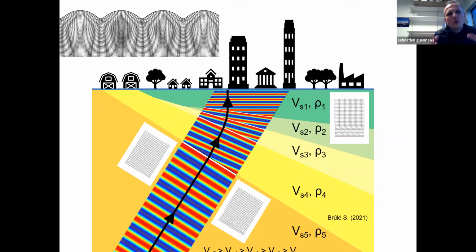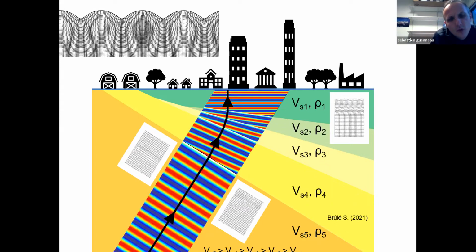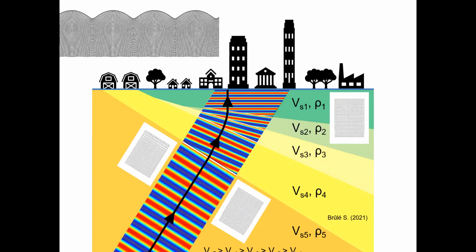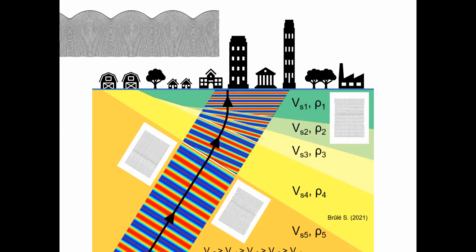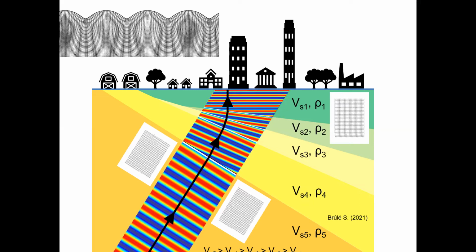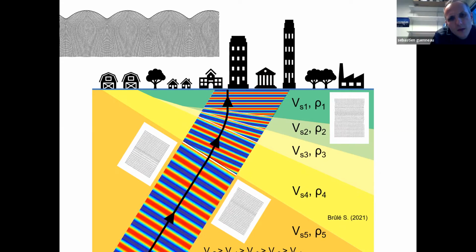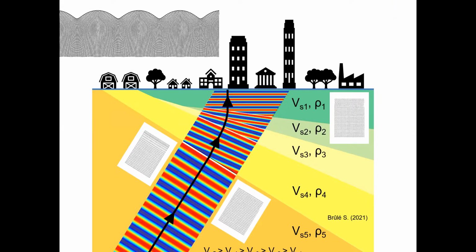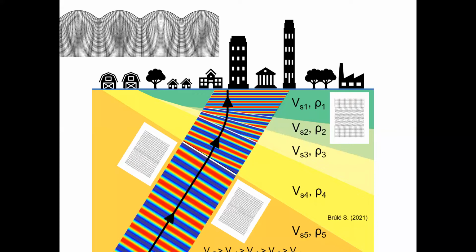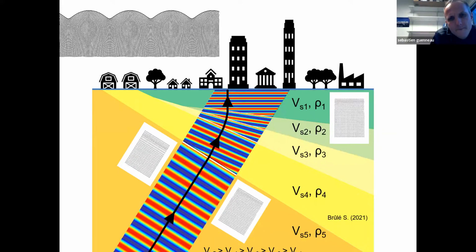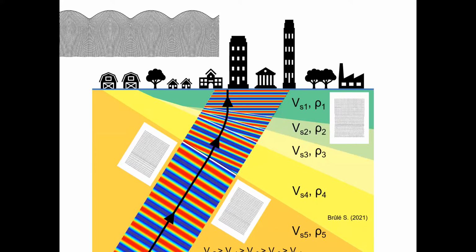So you mean the buildings should be further apart? I'm not sure I understand. No. You have to strictly design the amplitude, the relative displacement between two buildings with two different fundamental periods, because we have two different approaches to flexibility. Their relative displacement could be a problem because they can shock each other.